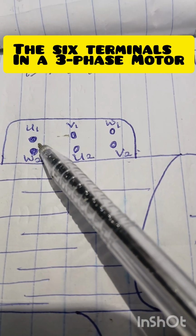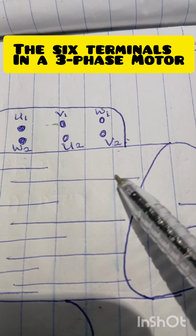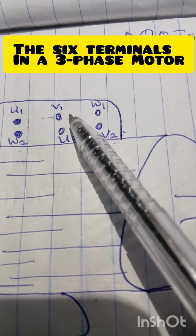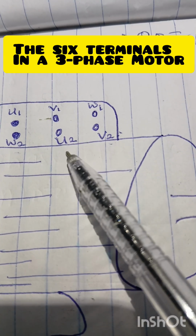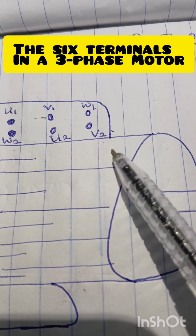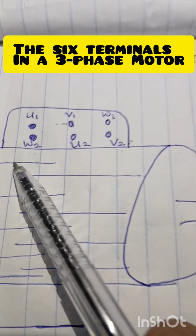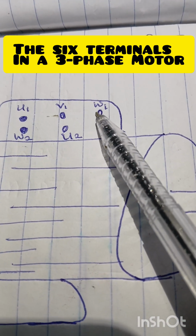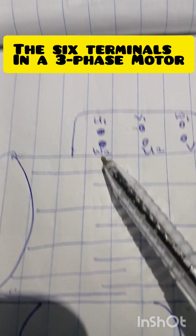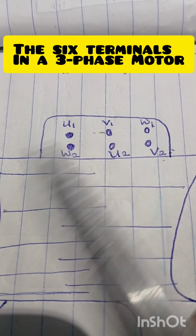So U1 is the start of coil U and U2 is the end of coil U. V1 is the start of coil V and V2 is the end of the same coil V. W1 is the start of coil W and W2 is the end of coil W. Those are the six terminals that we have here.